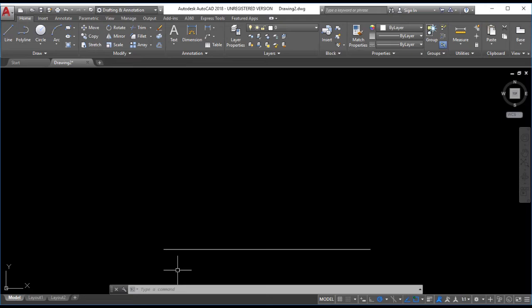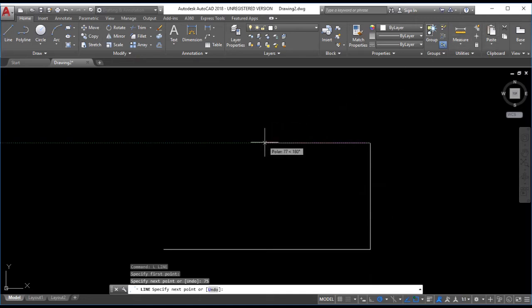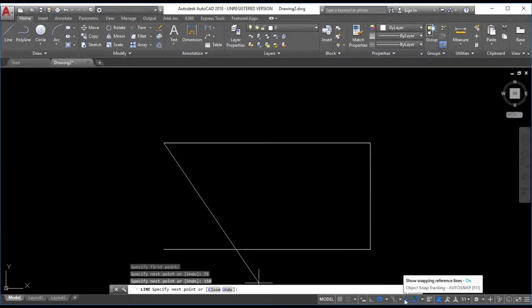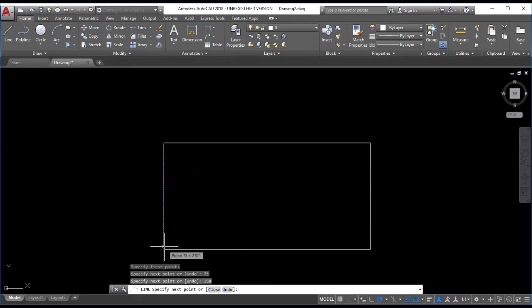It's now off, so I'm going to enter L again, enter, and just to select this point, I am going to enter line. Let's use 75, enter, and we move it to the left, and we are going to use 150 again, enter. And this green line is showing where we have our horizontal or vertical lines, or it is set at a 30-degree angle, so it's going to snap at every 30-degree angle. It's just another one of the tools down here that we use. Right, this one is called polar snap. So I'm just going to close here for now with the line command, escape.